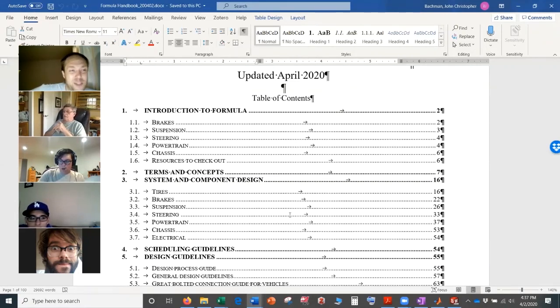But I think it's really hard to say. I mean, it's even hard to talk about all the angles when the car is just sitting still, more or less when you start to turn the tires, right? And then the car starts to roll, right? The angles really get nasty. But I think the basics are probably still the same. You want the tire to be vertical in those scenarios, and you probably still want some trail. So you don't want your trail to go away in those scenarios either.